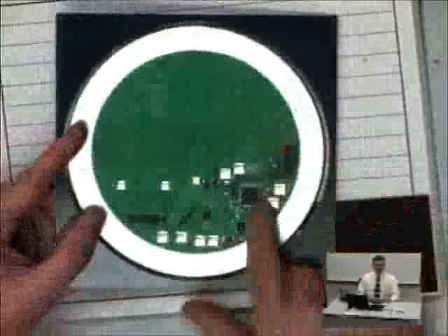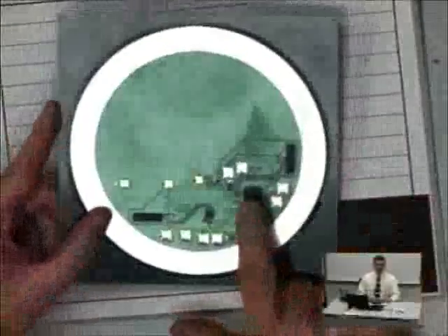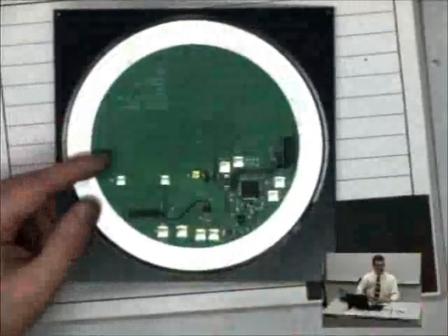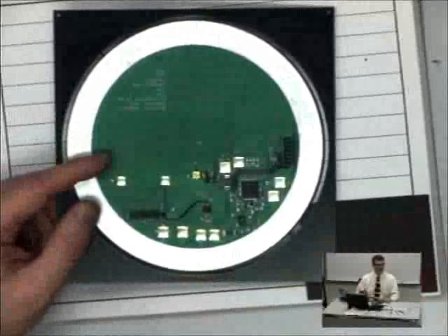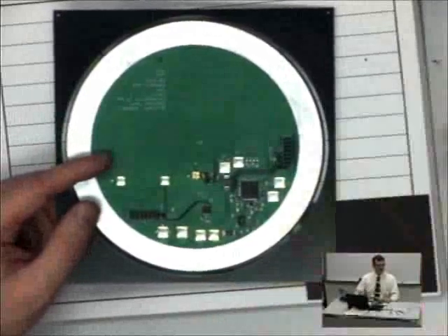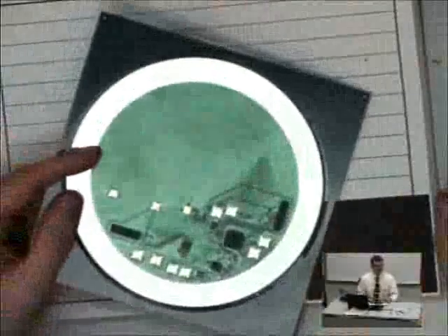All this guy does is measure the line voltage with a very low-powered microcontroller and digitize it. You see this little gold switch here? That's a load modulator that just switches between open and short, +1 reflection coefficient, -1 reflection coefficient. It uses that modulated backscatter to send the information back to an illuminator unit on the ground.